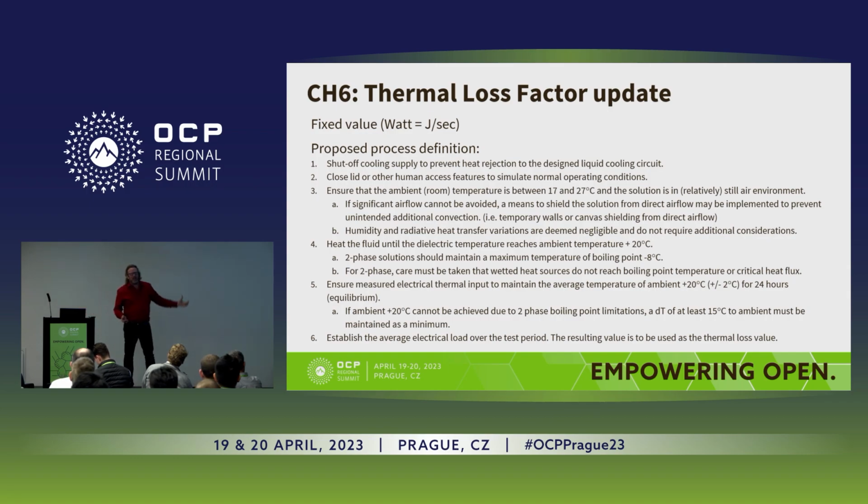As a starting point when it comes to immersion technology, we've decided to just at least have something to begin with, which outlines how much energy is not going to be captured by the water circuit, but is just lost to the environment, irrespective of whether it's radiation heat or convected heat. Right? There's a proposal that is still being evaluated which only applies to single-phase immersion cooling.